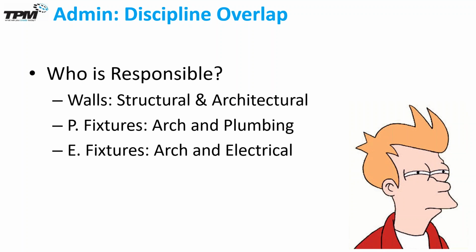Right? So if an electrical contractor is putting together your electrical model, he should absolutely be putting those electrical fixtures in there. Now, I'm not saying don't have the architectural light fixture locations in the architectural model, but at least have them turned off before you do your clash coordination.